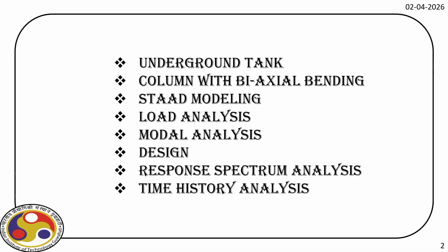That is also very important for seismic analysis and also wind analysis. But here in this course, we'll only consider earthquake load, which is applied as a ground motion. So the supports of the structure will experience that acceleration. We normally record those accelerations during an earthquake. And when you come to a particular site, that site has a design response spectrum. So we need to first make a spectrum compatible ground motion before we apply that to the structure. Again, I will not go into the details of how to generate a response spectrum compatible earthquake, because that involves some mathematical theories.